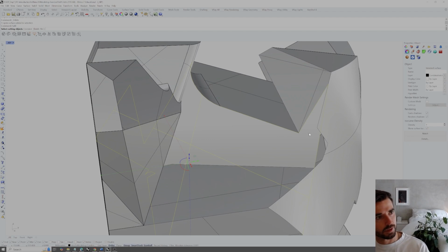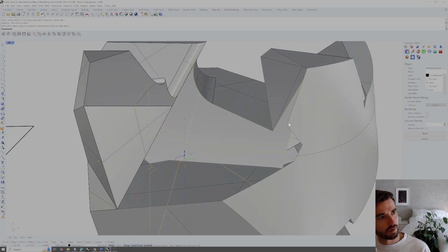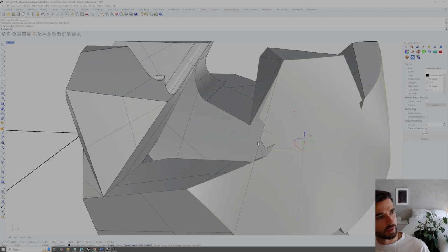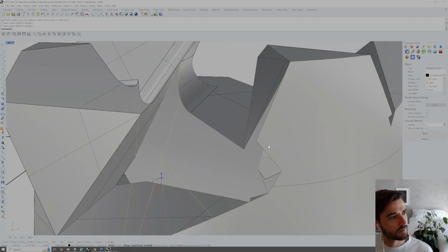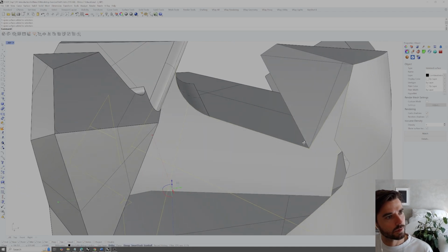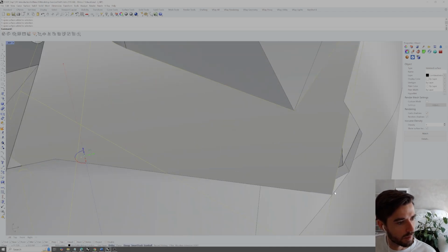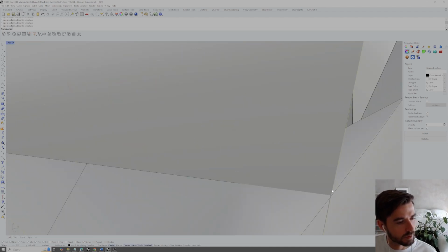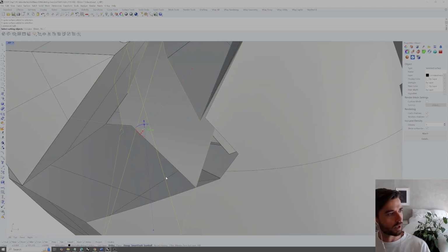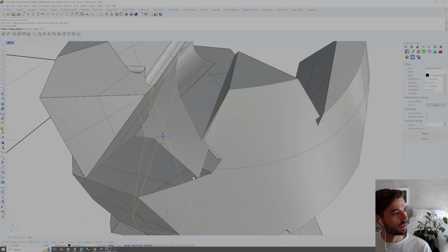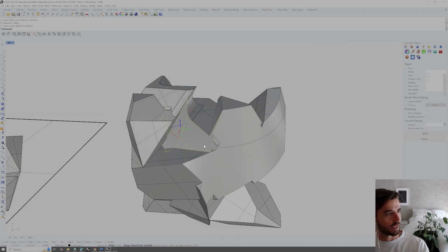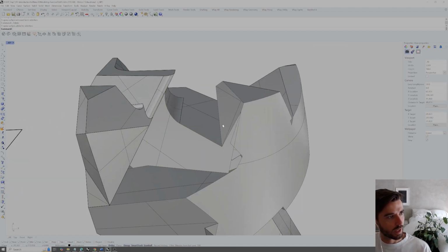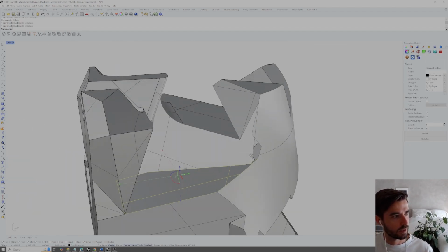You can take this surface and split the cone. It looks like it doesn't want to split, may not exactly cut through. So we can come back to that, and it looks like it might be having an issue there as well. So let me try again to split it with the polysurface. It's saying again that it's failed. Okay, now we've gotten it. So now I can go ahead and delete this extra bit. So we just have the portion of that polysurface that we need.